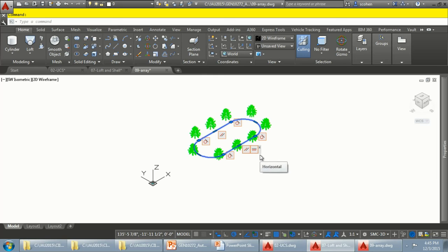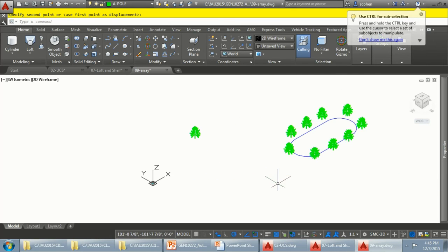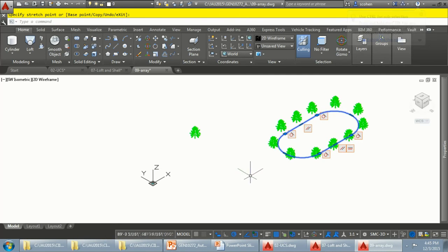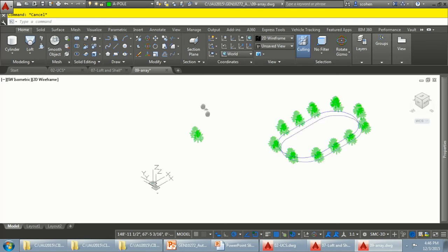This line, or this polyline, is constrained. So not only will, if I move the path, it moves everything with it. You don't have to worry, that's the one I copied. But if I change this, because it's constrained nicely, it automatically adjusts everything. So those are 2D constraints, 2D AutoCAD constraints. And I'm sure, well, it's the last day, but there were classes on 2D constraints. So that's a really nice option, okay?